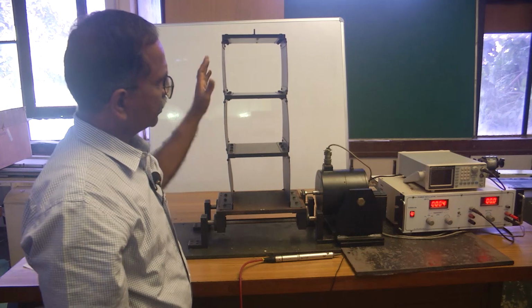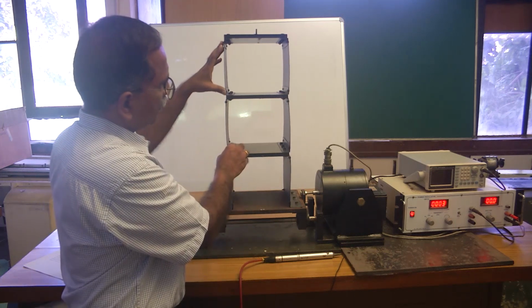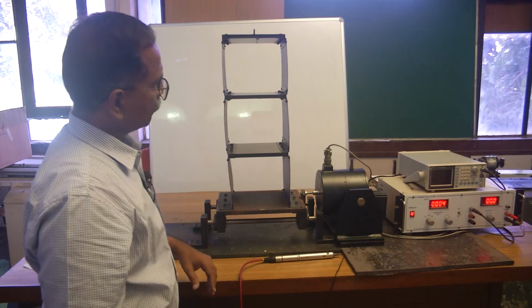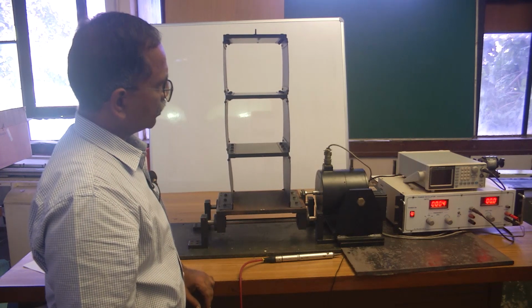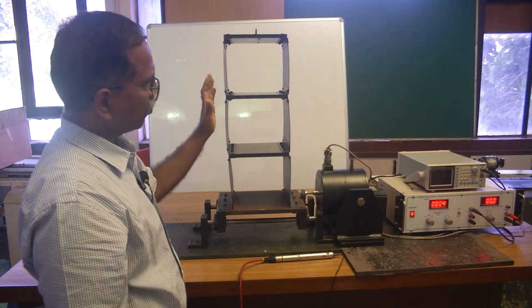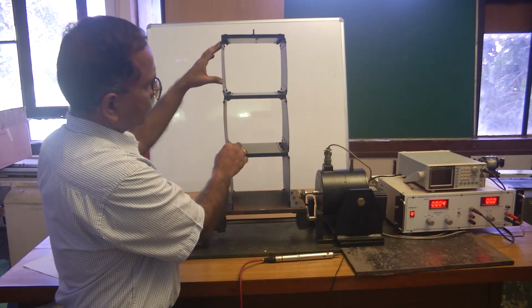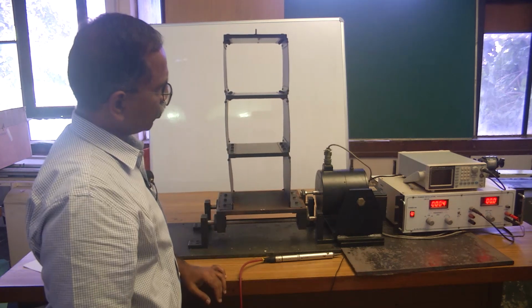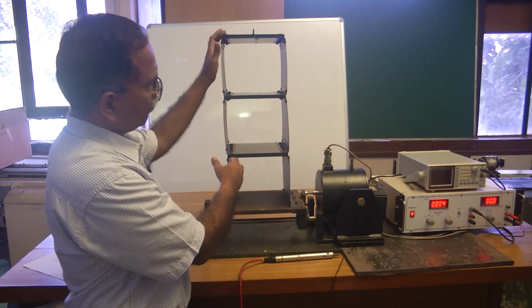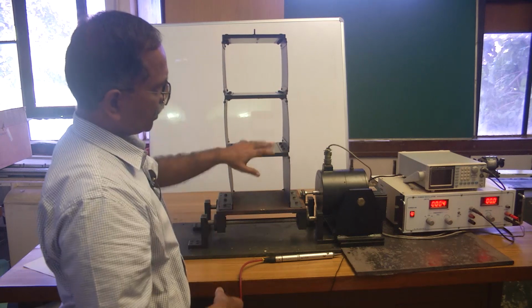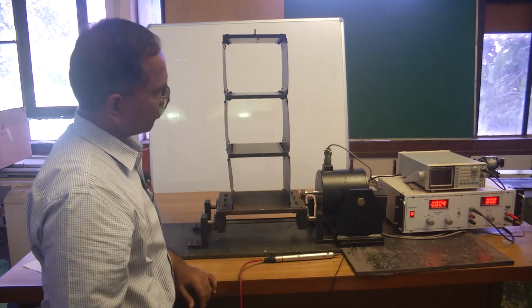In this case it has definitely moved in the first vibratory mode, the mode 1 displacement pattern. The mode shape number 1 was evident here, and you can actually calculate the mode shape based on the numerical values of the masses and the stiffnesses of these plates.